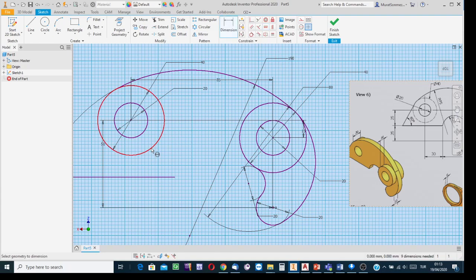Dimensional constraint from the circle. If you indicate the center, or if you indicate the circle at any point, Inventor will attempt to measure the diameter, but if you indicate one more point, then Inventor understands that your purpose is to input a dimensional constraint for locating the entity.